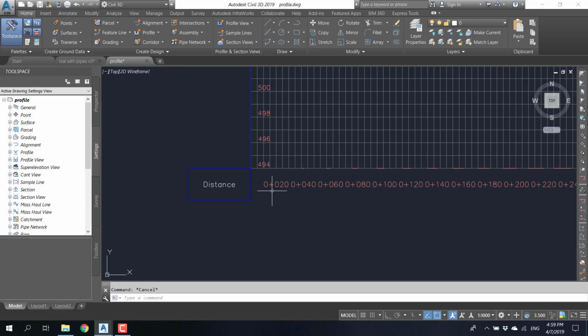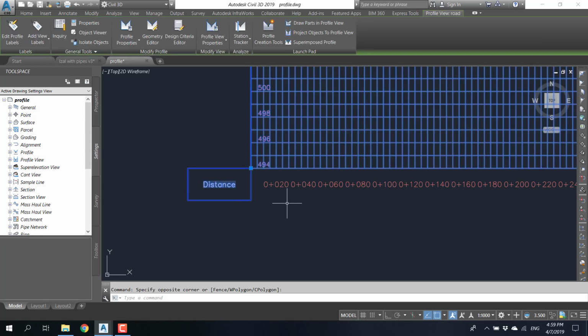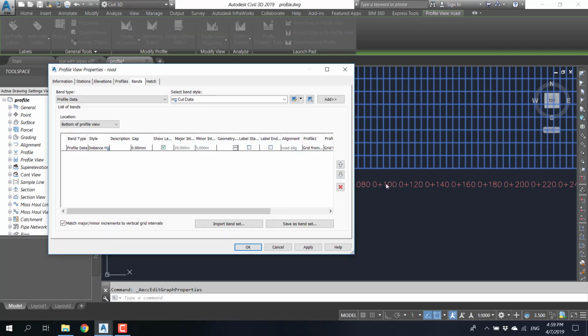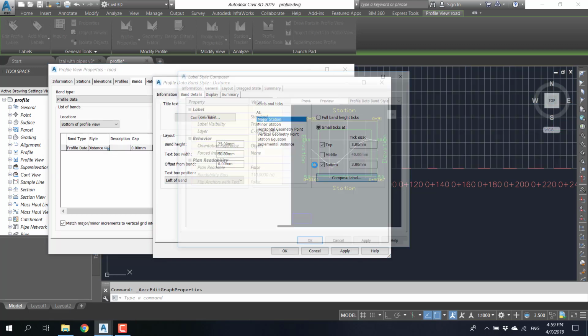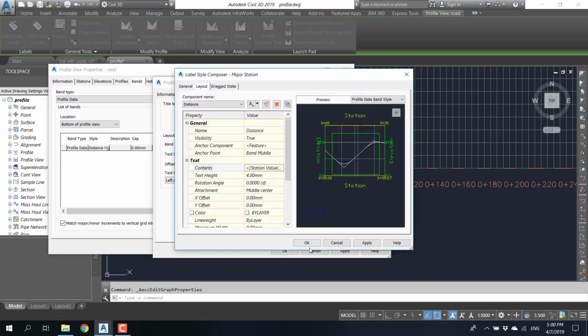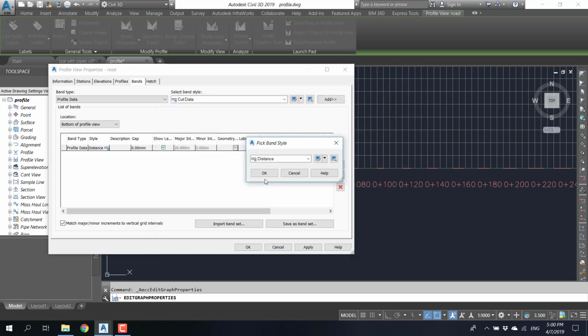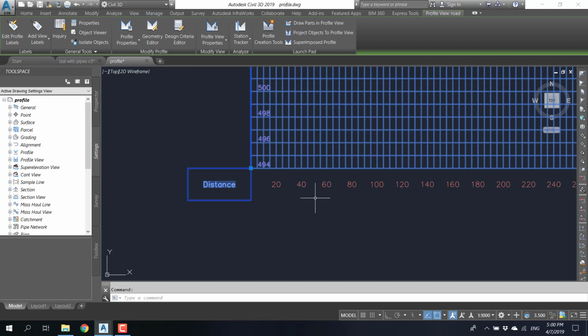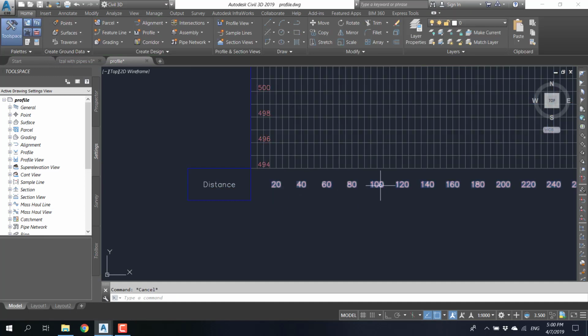Nothing changed but the properties. It moved down, but the values didn't change, and it's still a station because I didn't press on the arrow. These properties didn't change because I didn't press on the arrow after editing this one. So it's decimal, precision 1, press on arrow, now changed. Now it's only distance and in meters.